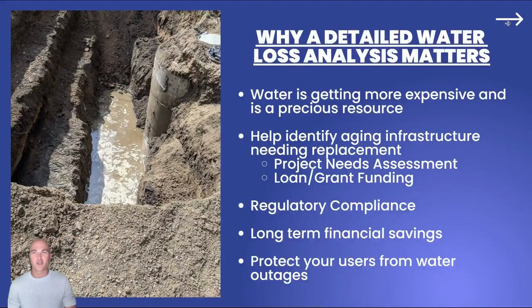Okay, so why does a detailed water loss analysis matter? Water is getting more and more expensive, especially in rural Colorado. It's expensive to buy, sell, get water up there, and so that's quite a big deal. If you've got aging infrastructure, you need to identify where things need to be replaced and how to come up with a priority list. Also, that's going to tie into your typical project needs assessments, which you're going to need to get loan and grant funding for your projects.